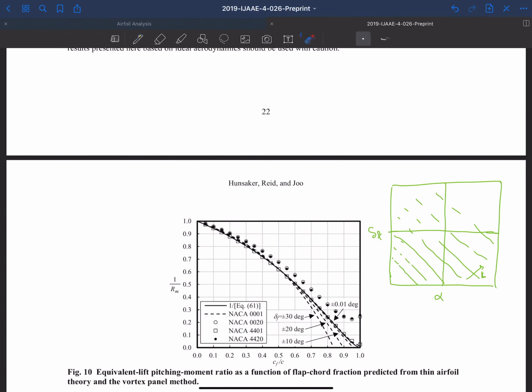And then of course, if you hold an angle of attack constant and increase your flap deflection, then your lift also increases. So these contours kind of look like this, okay? And then we went to the parabolic flap and we said, okay, so at this angle of attack, we choose an angle of attack, and then we say you have to produce this much lift that falls on this contour here. And of course, the deflection of the parabolic flap was a little bit less, usually between 70 to 80% of the traditional flap. But then we ran both of those scenarios through Xfoil to compute the drag.